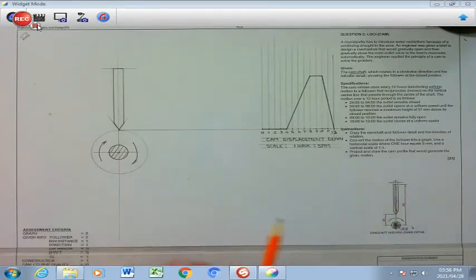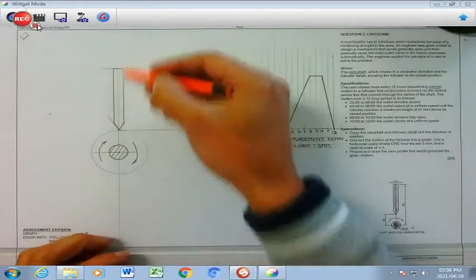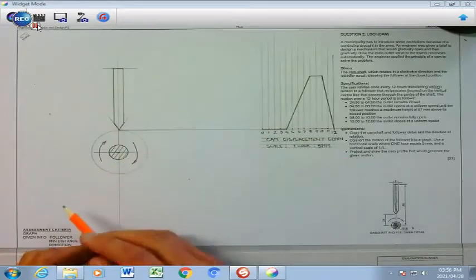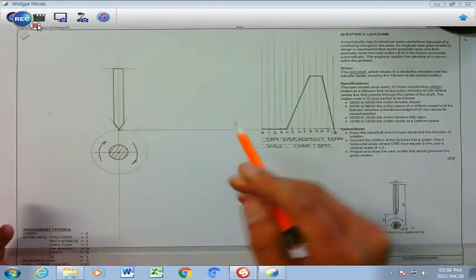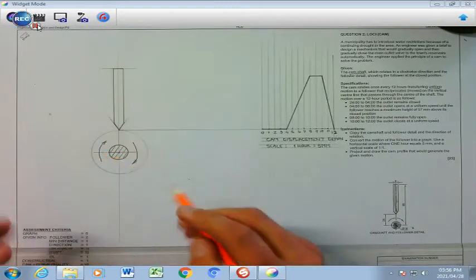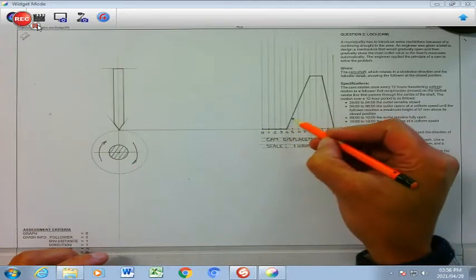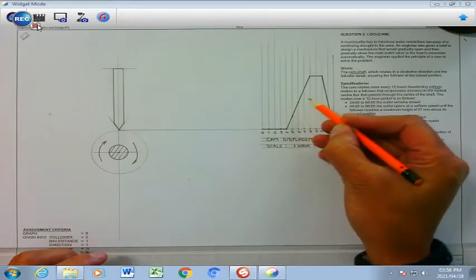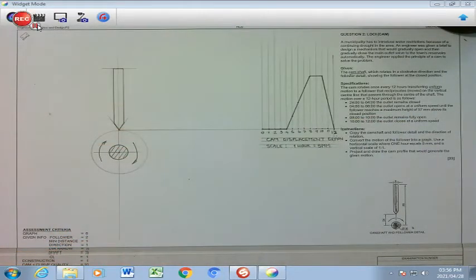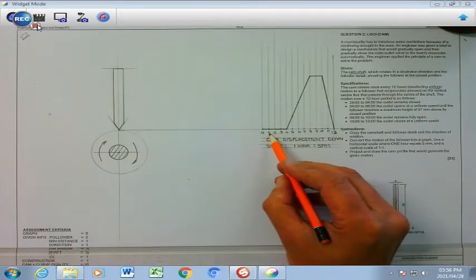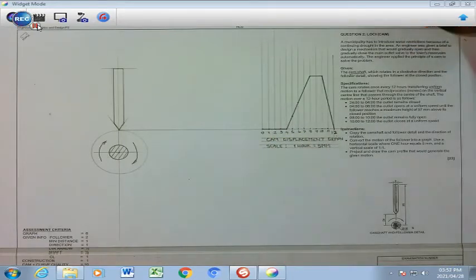The second part of my cam would be for me to set up the cam profile, and I'm going to draw my cross here and my divisions first, and then I'm going to draw my outside or maximum radius here, label it opposite to the arrow, and then of course I will take each of these specific points here, mark it clearly like that, and then transfer it onto my center line, and then transfer that onto the respective number that's corresponding with the hours that I have here. Let's do that quickly, and please pay attention clearly to how it's done.